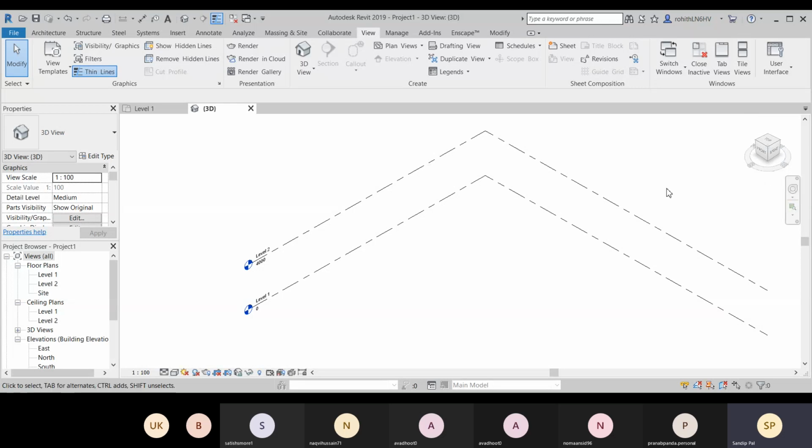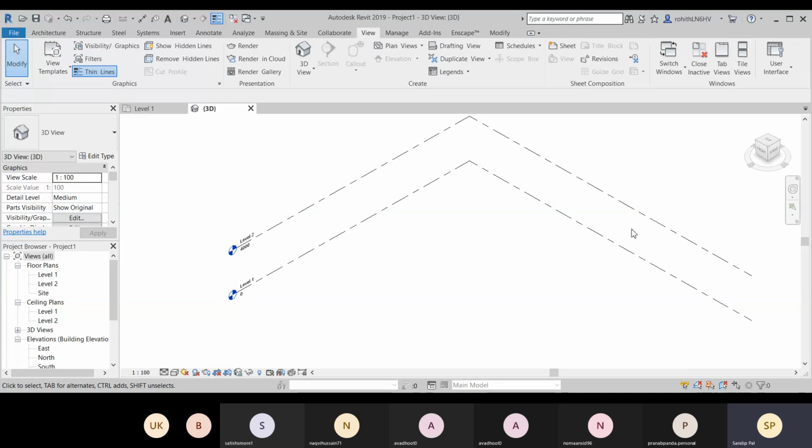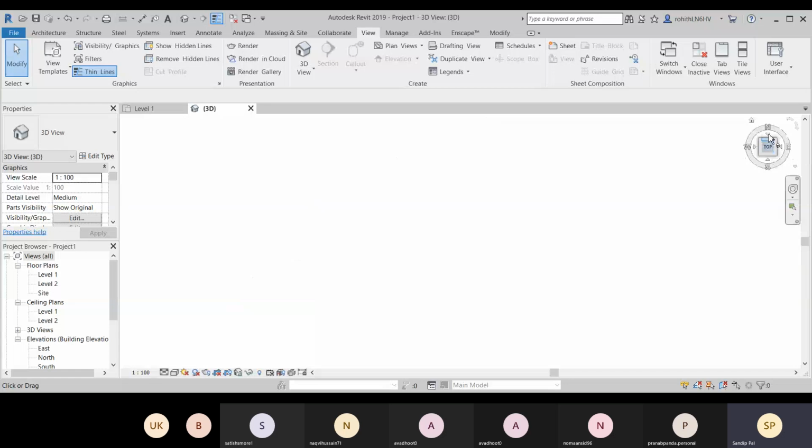So this will help you to have any view within 360 degrees, and within this space you can have any view. With the help of this, in any angle you can see it. So we have this view cube. You can switch to top view. You can see this is the north direction, west, south, and east direction is there, and this is the positive direction, that is anti-clockwise.